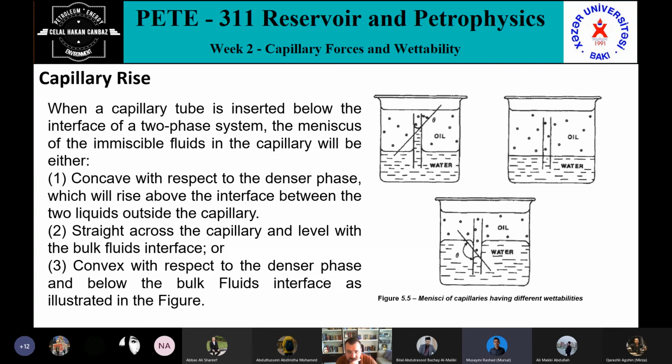So what can be the contact angle? It will be 90 degrees. Exactly 90 degrees. Correct. So the first one is water wet, definitely. According to the figure, it's strongly water wet. The third figure is oil wet, definitely, somewhere between oil wet and strongly oil wet, maybe 140 to 150 degrees. The second one has the same angle, so we can say this is neutral wet.